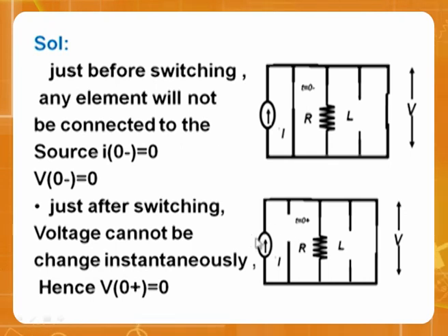Similarly, the switch is open, but the resistor is here. The inductor cannot change, the capacitor cannot change. Inductor same, no current. Capacitor same, no voltage. What is the final output voltage? Because this is shorted, this is 0. Please observe, 2 short circuits 0, 1 short circuit also 0. So because the capacitor is present in this circuit, the voltage is not changing.